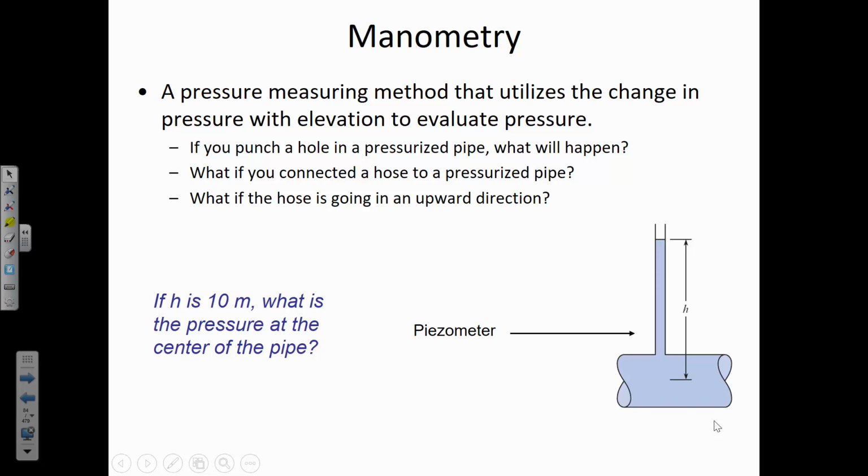So the typical water pressure in a municipal system, the pipes that are running through Huntington: on the low end, the lowest pressure they like to have in the pipes is about 200,000 pascals, not kilopascals. So the typical range of pressure would be 200 kPa up to a maximum of about 850 kPa. And they don't like it to go too much higher than that, because then fittings can start to leak. One system in the home that's particularly vulnerable to high pressure is water heaters. They would start to leak first. So think about what that means.